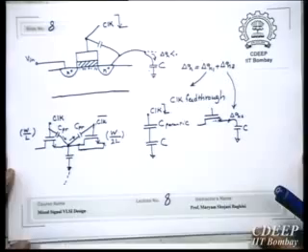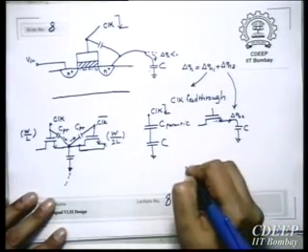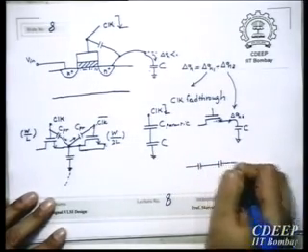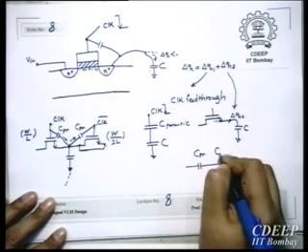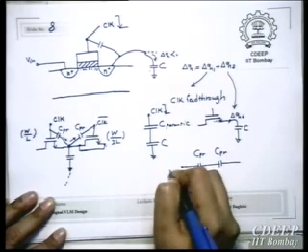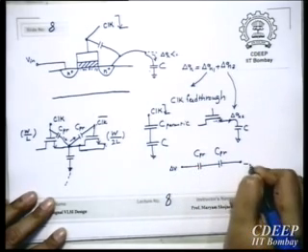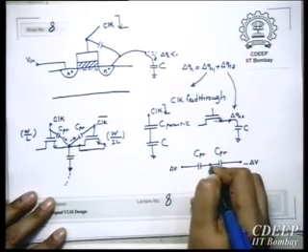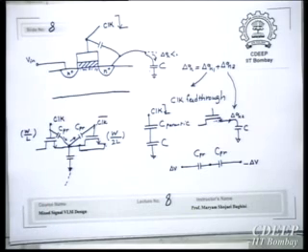Look at it in this way. You have two capacitors, they are equal. Here you have delta V, here you have minus delta V, and this will be 0. This is happening at the clock transition, not when the clock is stable. At that time there is no change, capacitors are open. This happens during transition.